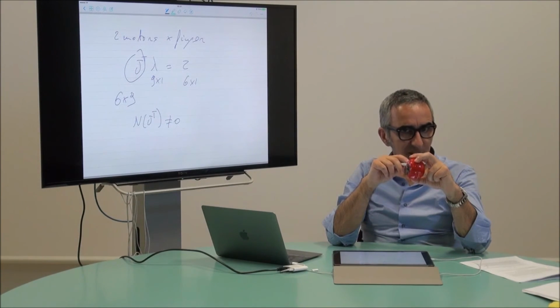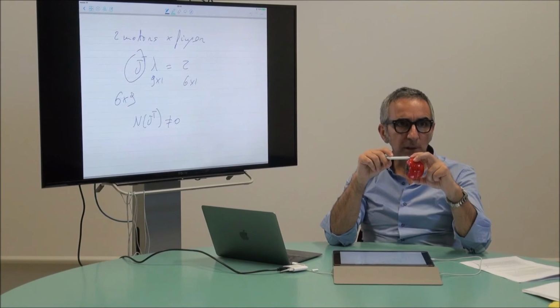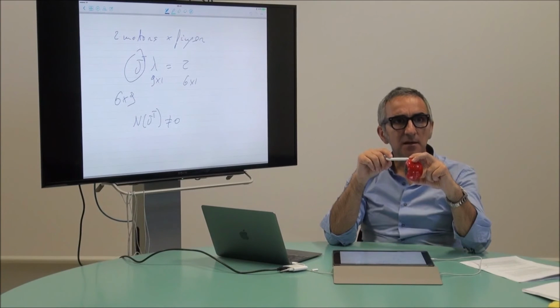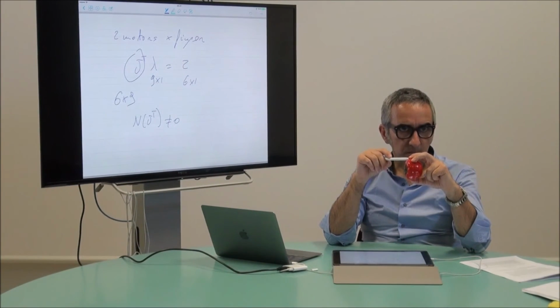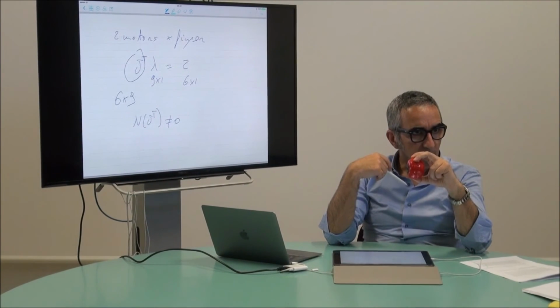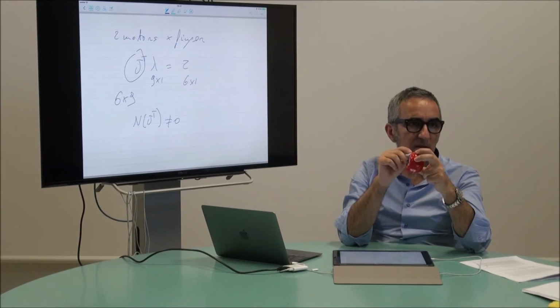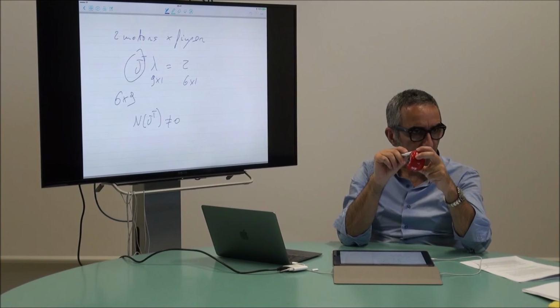So if you have fewer controllable torques than directional forces at the contacts, you cannot apply the forces that someone gives to you. Okay? And in my opinion, this is the reason why we have 3 independent joints, 3 independent motor controls per finger.